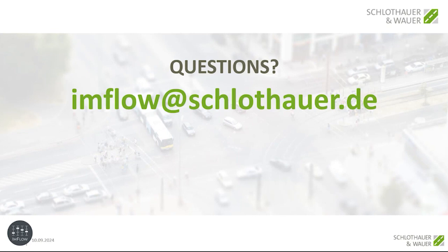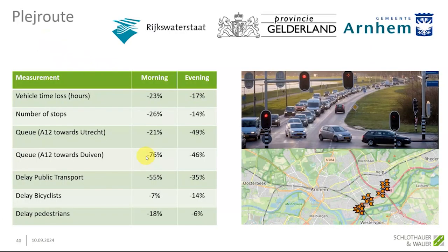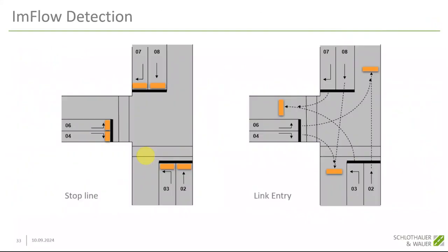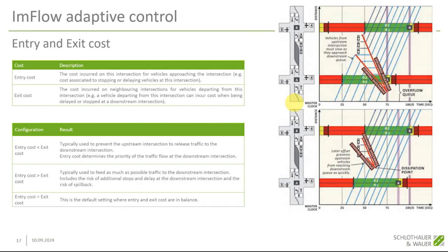So it's running on the CPU of the TLC, and the TLCs are talking to one another. Every TLC is always getting the information of the neighboring intersection. There's a better slide for this, but I don't have it here in my set right now. You have to imagine that the information about the next 60 seconds, the planning for the greens of the neighboring intersection, the upstream signals and the downstream signals, are also part of the optimization at my intersection.